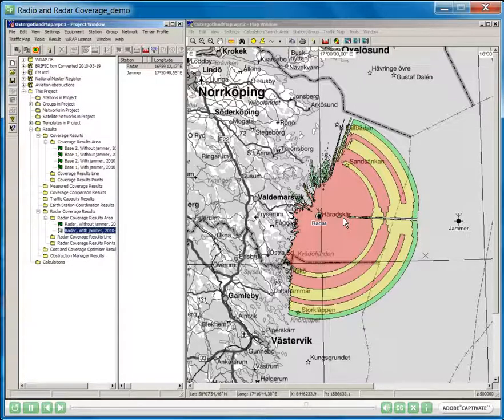And there is some effect to the visibility of the radar size also a little beyond this very narrow beam. The width of this blind sector is basically directly related to the beam width of the radar antenna, naturally. When the radar beams away from the jammer, it attenuates the jammer a lot, so it will not be so much affected.